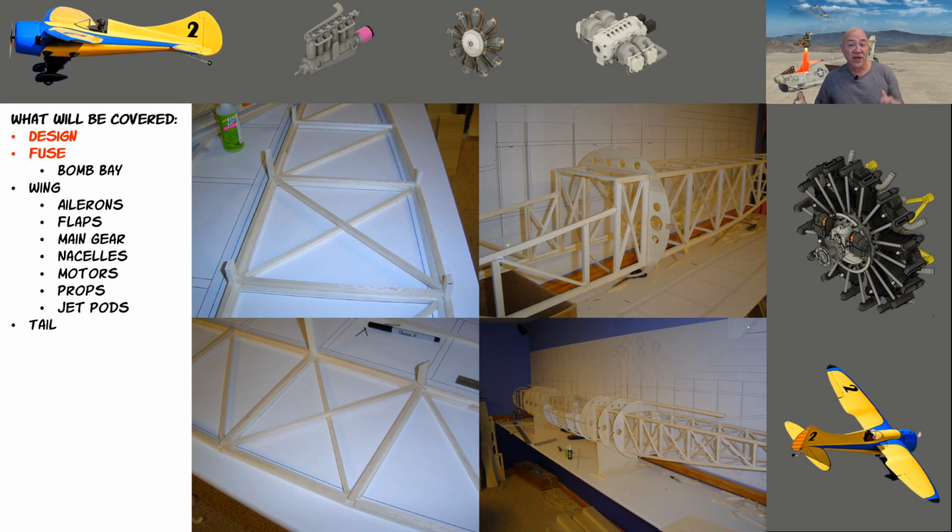Well, if you think about full-scale airplanes, flying a Cherokee, it's got a pretty beefy landing gear. But you land hard on a Bonanza, because it's a retract, and you might damage those landing gears. With model aircraft, it's the same thing. If you're going to build really light, you need to be a pretty decent pilot. But this airplane was going to have such a low cube wing loading that it was going to fly in between a glider and a trainer. So there wasn't going to be that much shock unless you just really screwed up a landing.